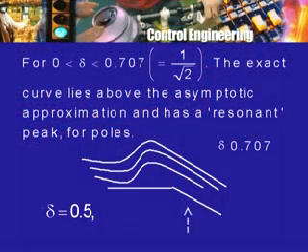If you want an operation to be over in 5 minutes, you do not want your oscillations to last for say 1 minute of it. That is too long a period. Therefore, generally delta is not small, certainly not as small as 0.5 or less than that. It may even be greater than 0.707, and when that is the case, the error really is not very large. So, one can get a good qualitative assessment by simply ignoring this error and using the low frequency, high frequency asymptote approximation.